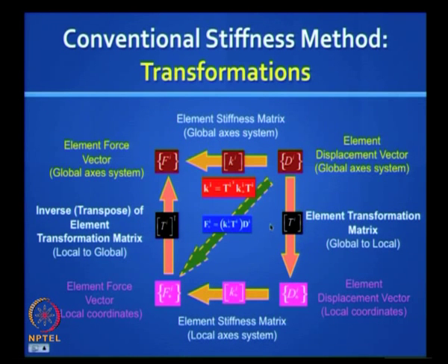First identify the coordinates, develop the Ti matrix, develop the element Ki star matrices, do this operation first, then do this operation, put the linking coordinates and assemble your structure stiffness matrix. First assemble your matrix element wise and then assemble the structure stiffness matrix. After you solve this equation and get the unknown displacements, directly use this to get your member end forces.